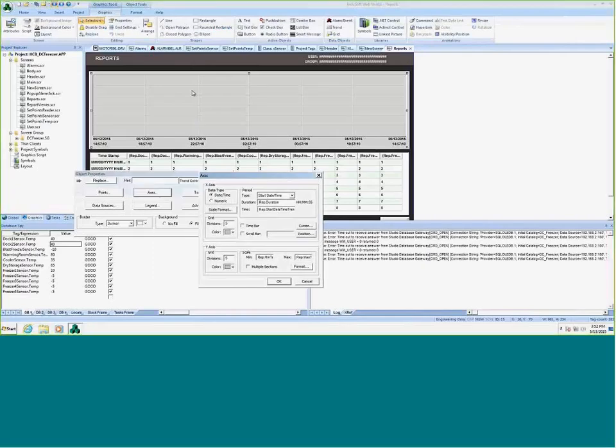So this is a trend view object. Double-click it to get the properties, and under the axis, this is where you define the axis down below. So you have the scale for the y-axis, that's not the right one. That's defined off of here. This is your start date for the x-axis, and then a duration, and that will be this date, and then over here is adding to the duration. That's how you get that to show up onto here.